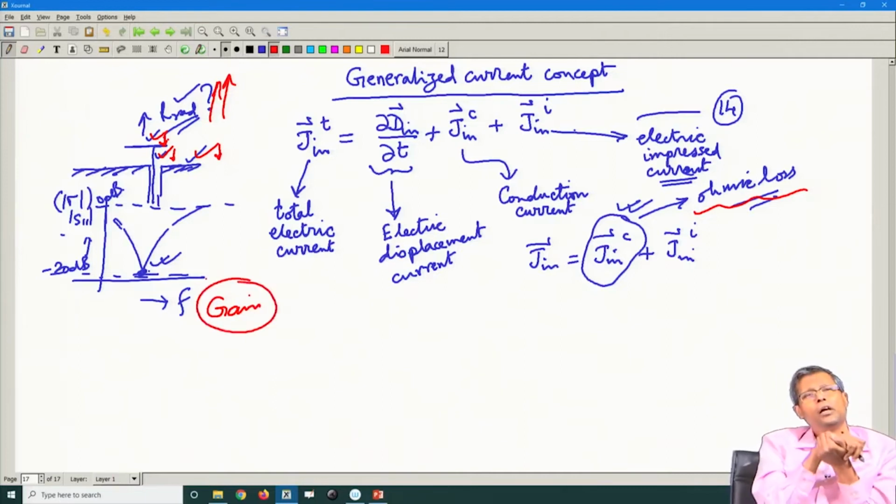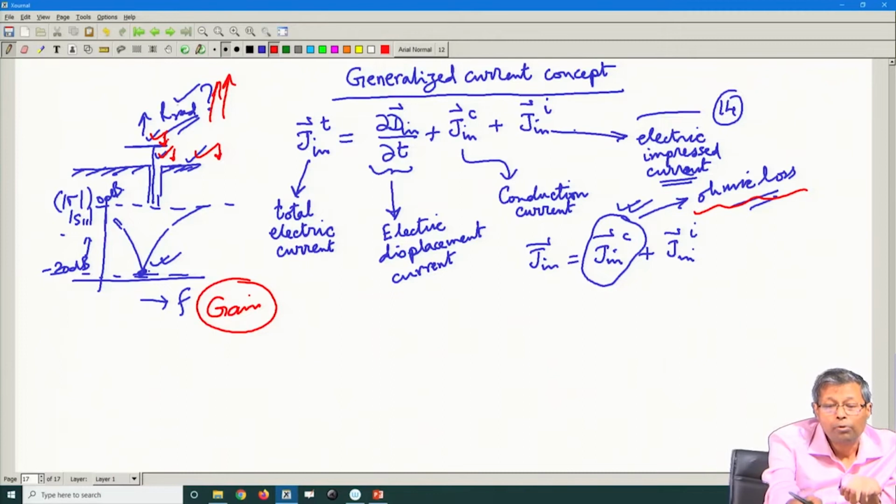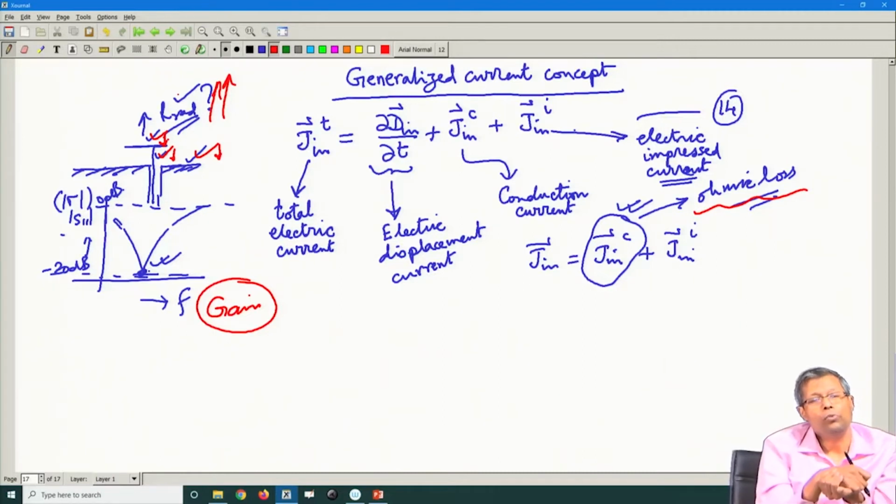If we measure or simulate the antenna gain and we get a decent gain, that means we are radiating a decent amount of power, and most of the power probably is radiated and we need not worry.